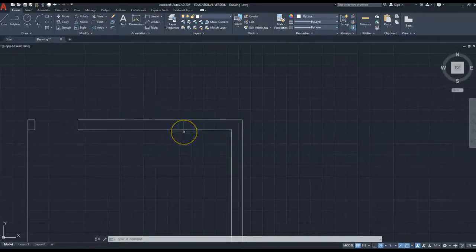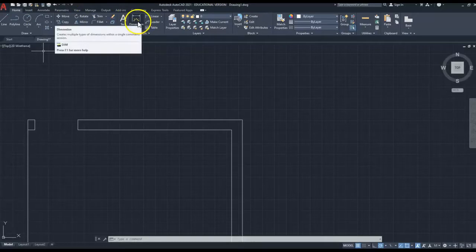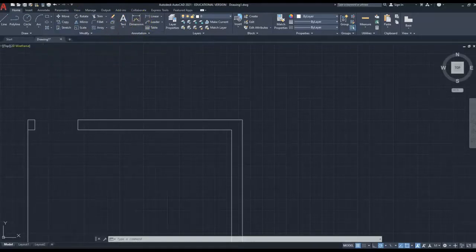I mean, I would, as a bricklayer, I'd always want something central, but it's central from the outside, so as it works in brick. So from the outside, it looks central. Some architects prefer it to look central on the inside. At the end of the day, it doesn't matter as long as there's a window going in. But first of all, I need to know what that length is. So if I click, I mean, again, this is only the way I do it. You could use the dimension checker up here, which is great, but I find it easier to select line.